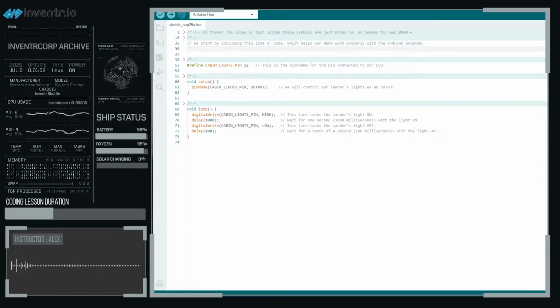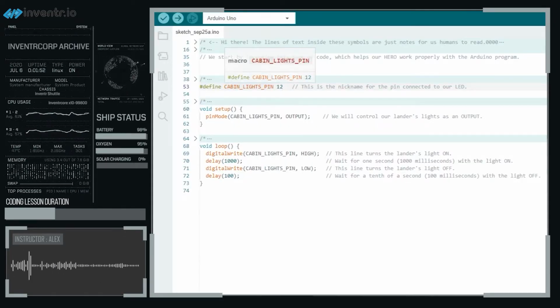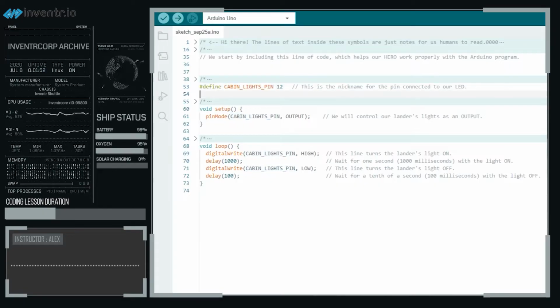Just like we saw with the LED built-in name, the Arduino IDE gives us the ability to give names for values we use in our sketches. A common way to do this is to use #define. Since this is a variable that will not change, our engineer has put the variable names in all caps. That's just his way of signifying that something is not going to be changing. As you can see, other variables in later sketches will use a combination of capital letters and lowercase letters.